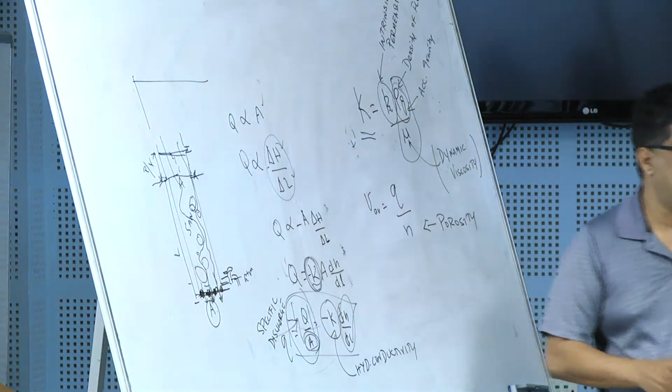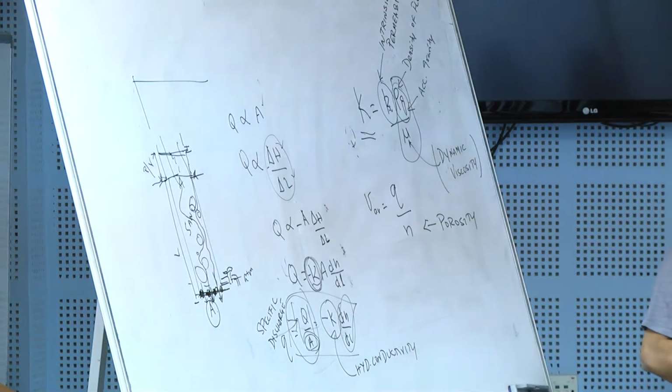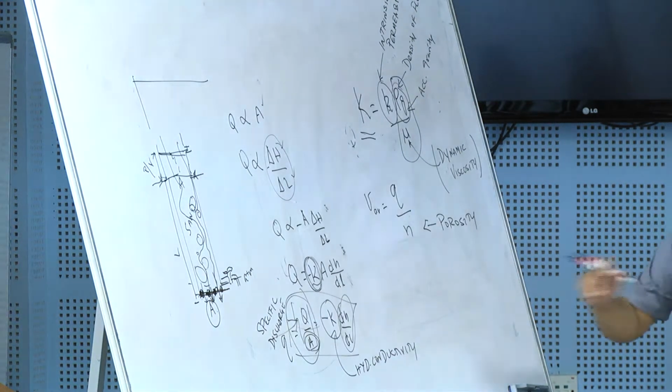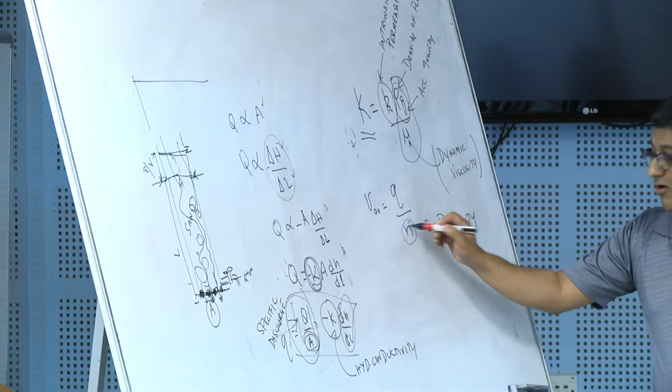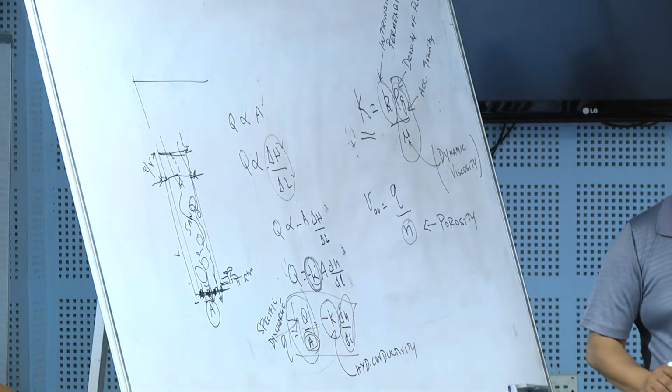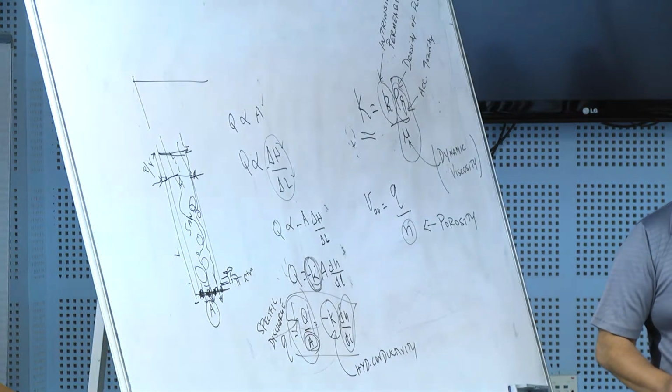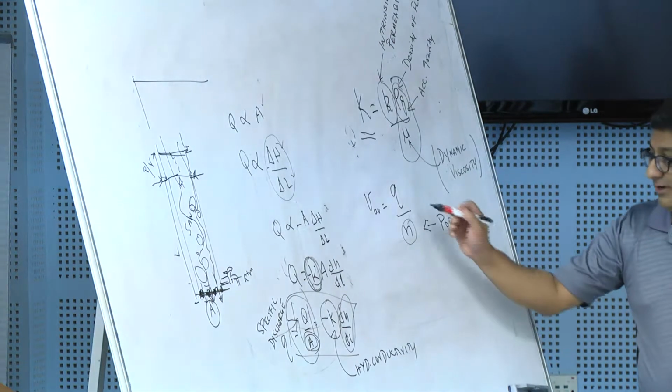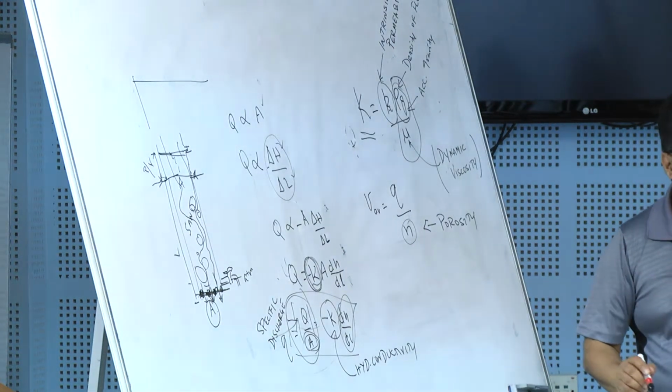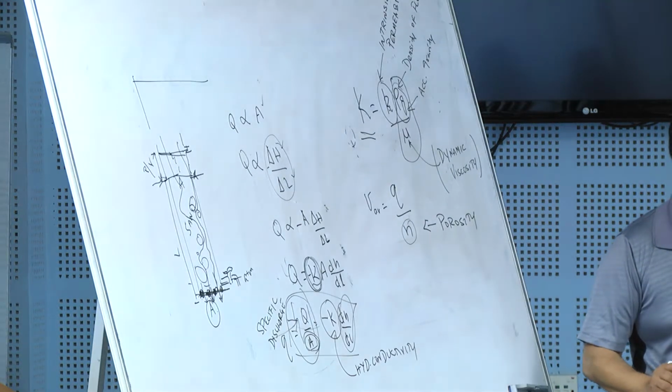N is your porosity. Because the porosity gives us the fraction, for a unit length, in the volume, if you just look at the area and take a unit height, what it's telling us is, the porosity tells you the fraction of void space, and the water is only moving through the void space. Whereas the specific discharge is the water that's moving averaged over the entire space.